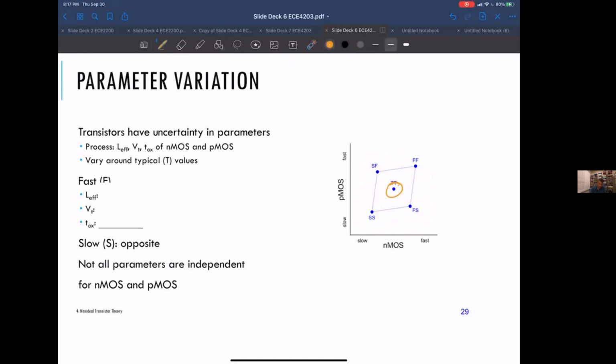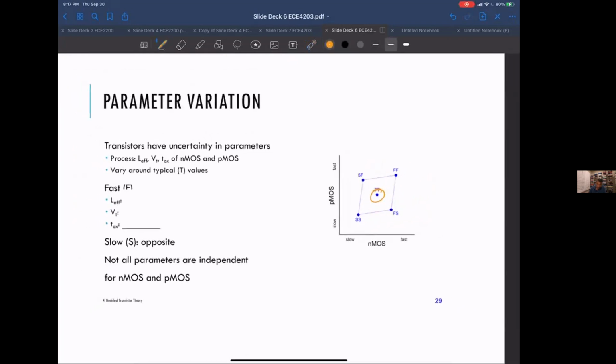So the stuff that makes for a fast corner, like I said, the foundries wrapped a bunch of stuff into the fast corners. It's basically short transistor lengths, low VTs, and thin T oxides. And so anyway, the upshot is you have to worry about designing around all these corners, or be willing to basically lose parts, which means your prices are going to go up. So it's kind of a case of careful design versus pricing.